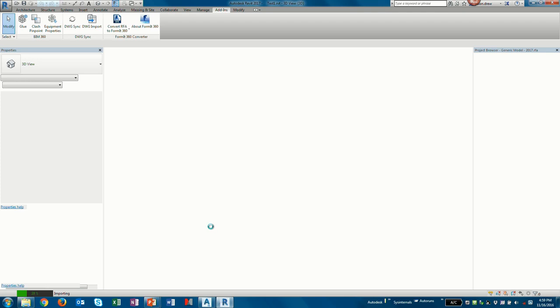While that's running, I will say that you have to watch out for your XREFs. For example, in that Area 1, I had the pipe and equipment, and had the steel XREF in there. If I have an XREF as an attachment type, it'll just bring it in with it. If you use overlay, it'll skip it. So depending on how you have your XREF set up, it'll have an impact.